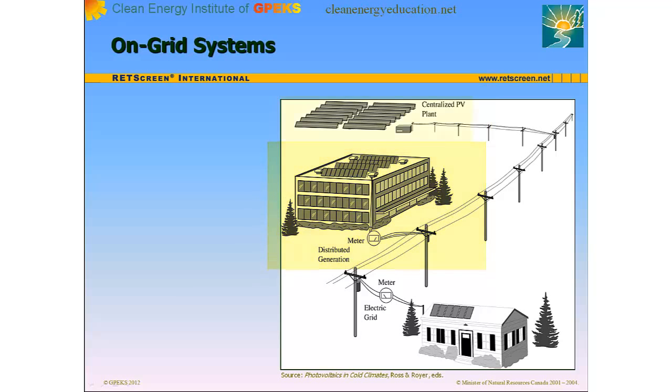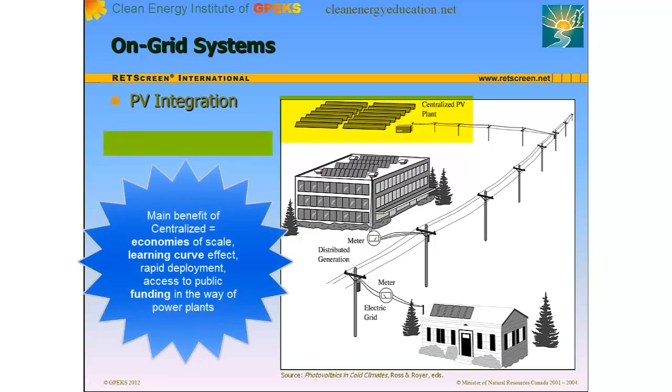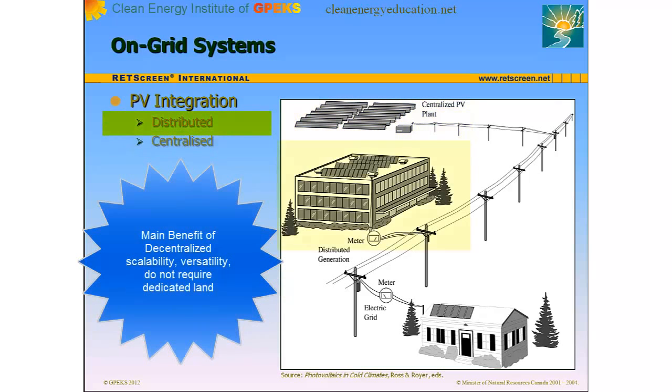The centralized approach is familiar to the utilities accustomed to conventional coal, hydro, gas, and nuclear power plants. In general, this approach facilitates system control, operation, and maintenance and leads to economies of scale. It is questionable whether these advantages are significant for photovoltaic systems, however, due to photovoltaics' inherent modularity, simplicity, and reliability. The distributed approach, though inappropriate for conventional power plants, is applicable to photovoltaic systems.